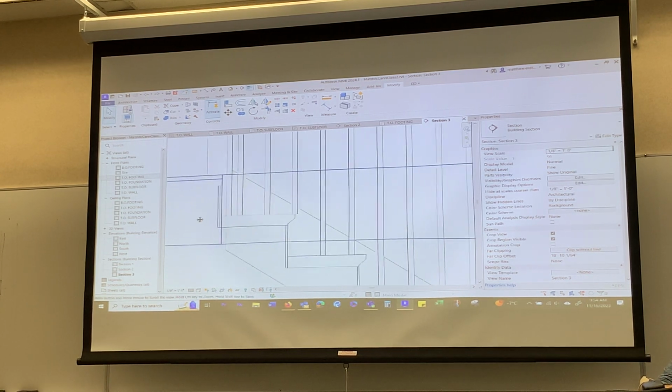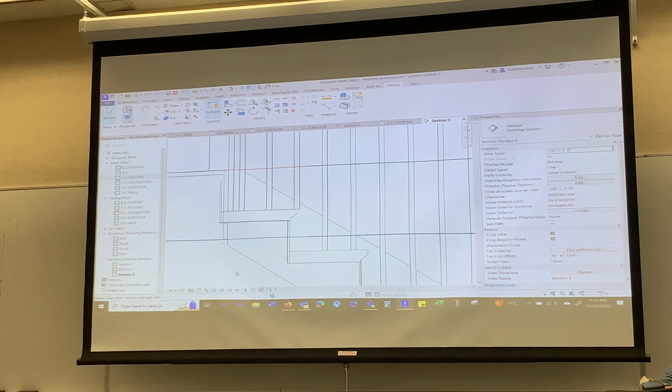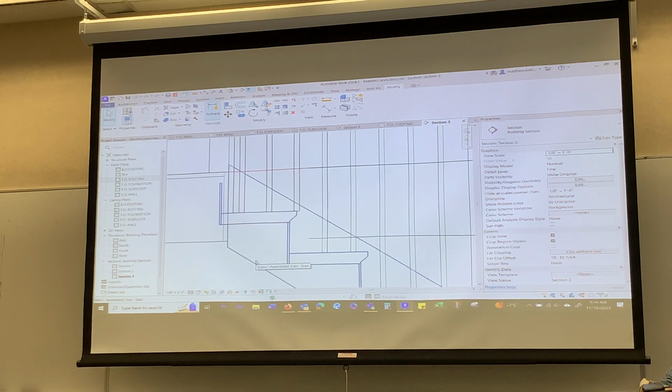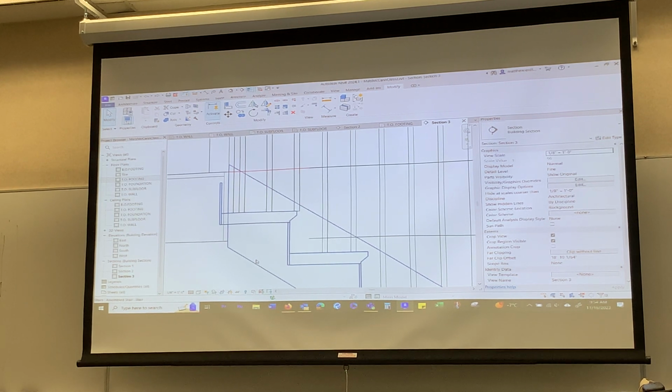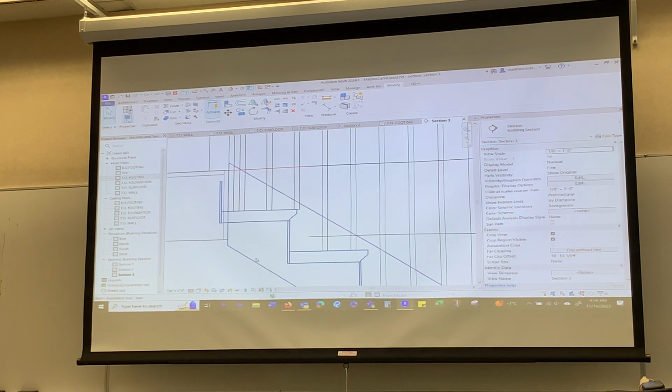Undo. So there's my stairs. See that plate there? They've done that because this is kind of how they do it. They nail it to whatever header is there. Usually there's an LVL or something across there, or maybe it's a double joist that's been filled, so it's flush. You need something to screw those stairs to, right? And they've got this plywood on here.